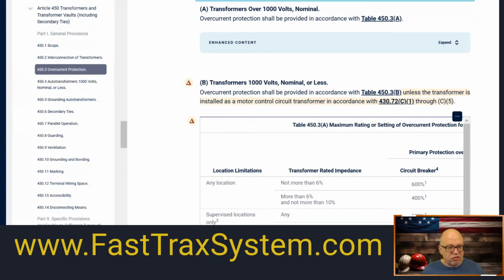They typically, if it's just a single transformer installation, then they'll go up to 125%. And then they'll size the conductors to 125%. So that same transformer that we were dealing with, that 480 transformer primary, we'll just do it at 75 kVA. So 75 kVA would be, let's do 480 times 1.732 again. So it's 831.36.